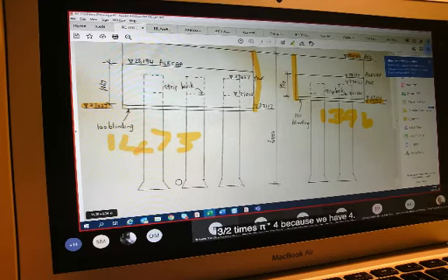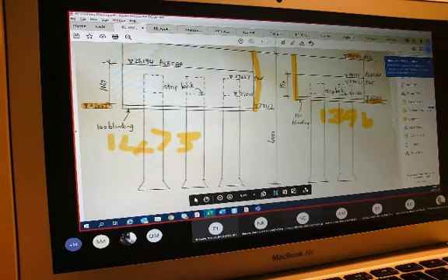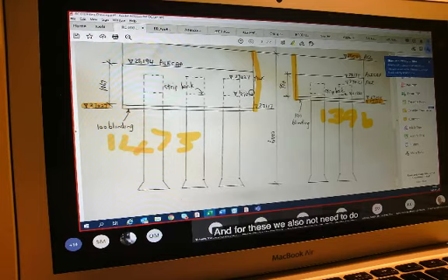So it will be 0.24 by 0.24 by 0.32 times pi times 4, because we have 2 of those sets of piles as per the information that we were given on the drawing, and that will then be multiplied by another 2. So in total there will be 4 of those piles that we need to deduct.